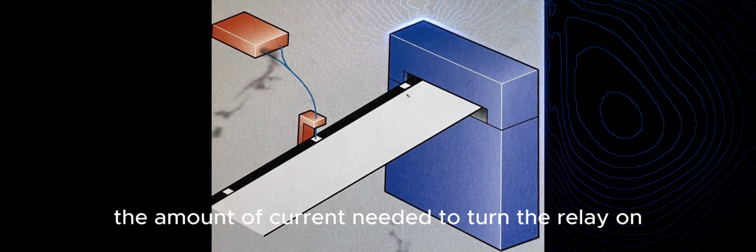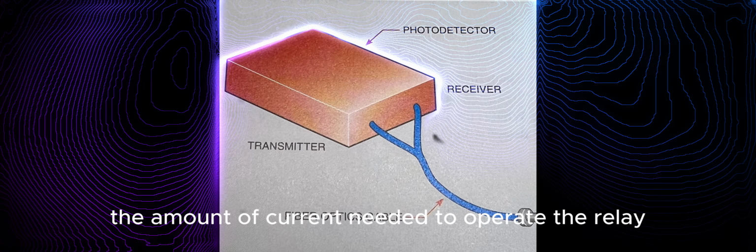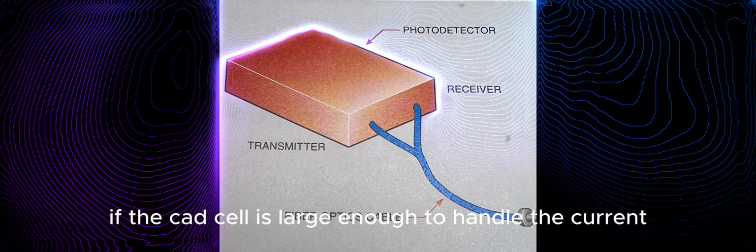When the CdS cell is in darkness, its resistance is high. This prevents the amount of current needed to turn the relay on from flowing through the circuit. When the CdS cell is in the presence of light, its resistance is low. The amount of current needed to operate the relay can now flow through the circuit. Although this circuit will work with the CdS cell, if the CdS cell is large enough to handle the current, it has a couple of problems.